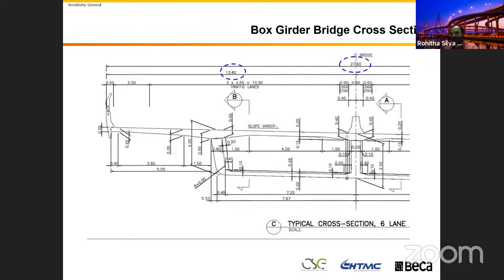The reason I'm not going to do that is that if you design the bridge to a different standard, the loading on the bridge is different. The live load on the bridge, if you use the Australian standards at one end, and if you use AASHTO, is at the other end. So when you are designing bridges to a different standard, these member thicknesses won't work. You can't just copy this and use it in another standard.